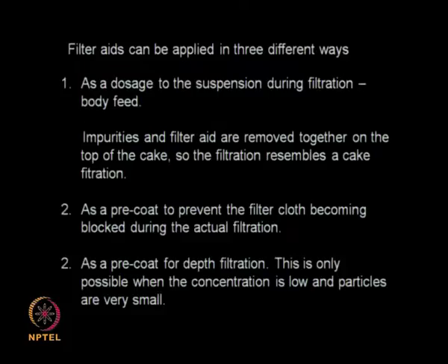What happens is the solids settling on top of my filtration unit and the filter aid settle together, so they can be removed together. It is like a filtration process where I have the cake as well as the filter aid retarding the flow of the liquid.